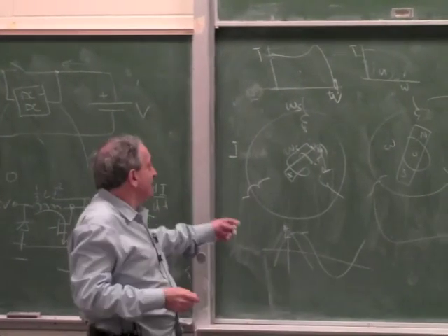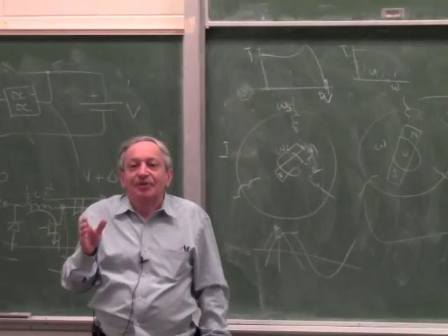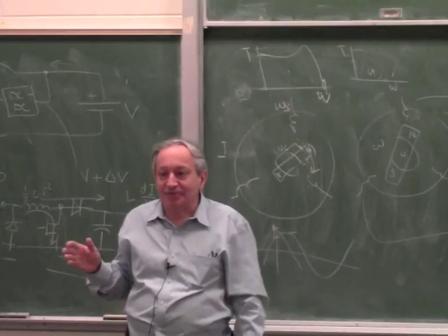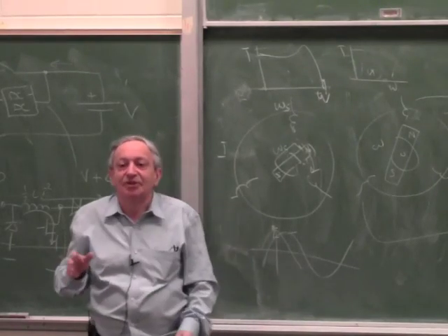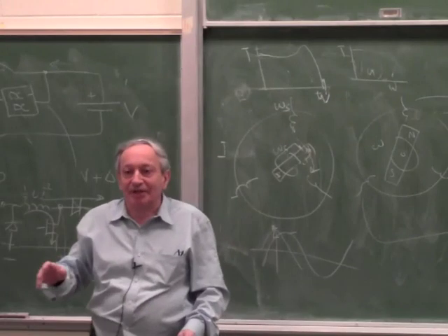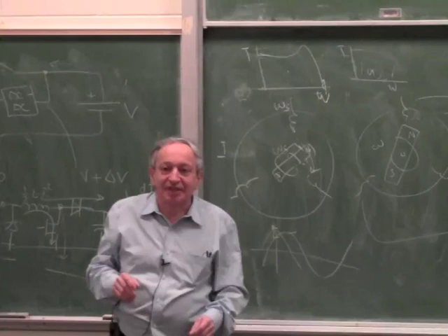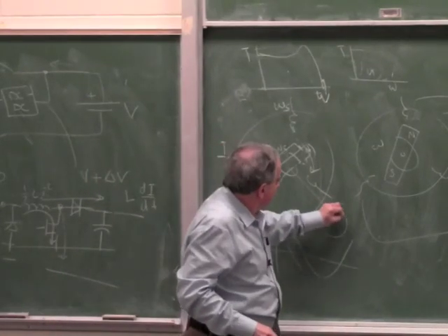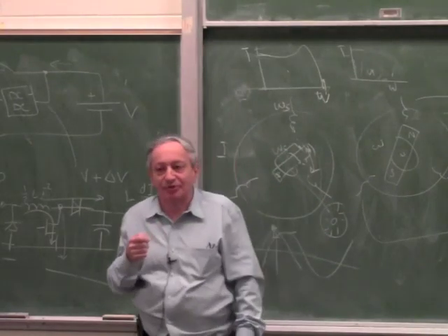And that's how it's done in electric cars. That's how the Tesla works. And the way it works, because there is no synchronous speed in an electric car, because the car can go at any speed, is as soon as you put your foot on the brake pedal on a Tesla, or you drop the acceleration pedal, there is an encoder on the motor. There is a shaft encoder which measures the actual speed of the motor.